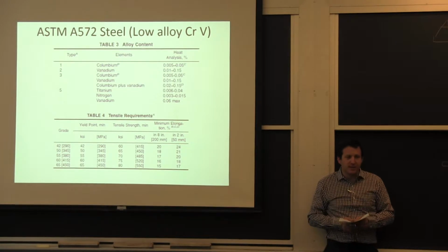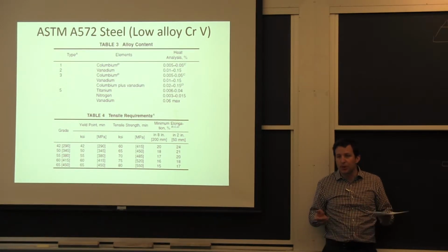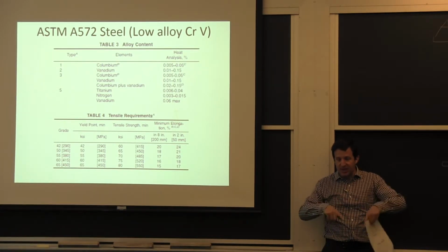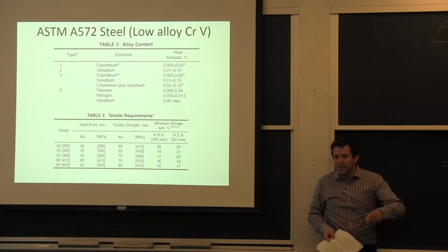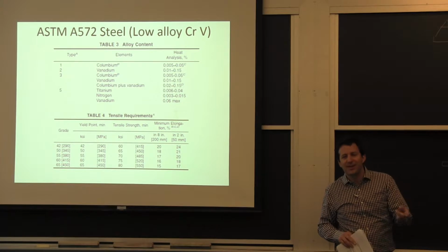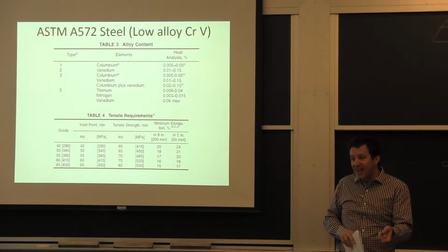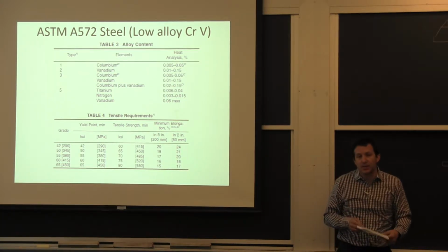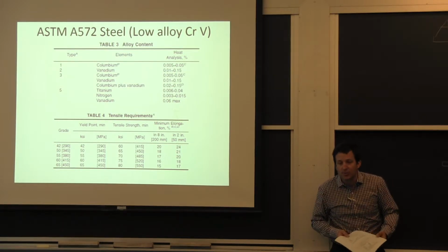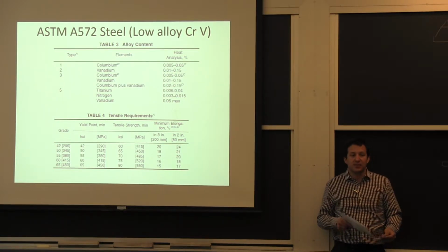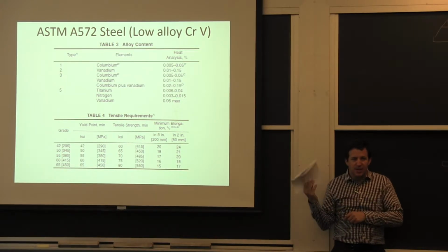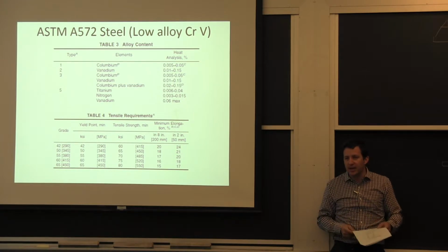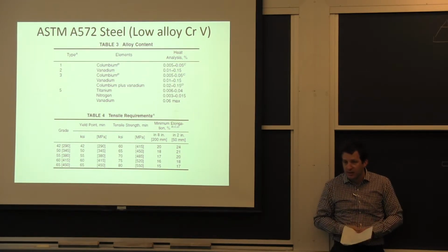The dog bone there is very typical for sheet products. So all you need to do is cut it out, use the overall thickness, and run it. If you've seen, it was machined a little bit. There was an alkali treatment on it, so there was a little bit of extra protective layer for that specific piece of aluminum I was testing. And the spec tells you to test it with the extra anodizing.